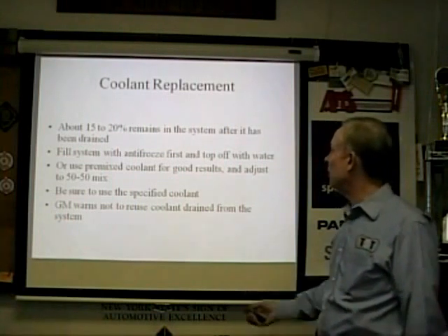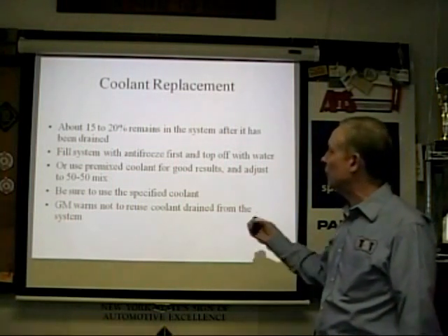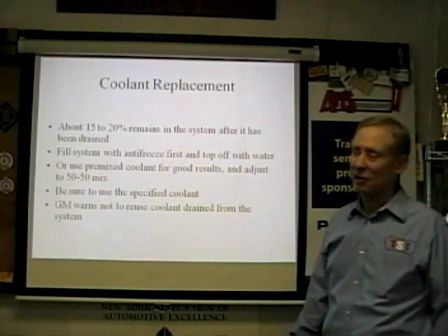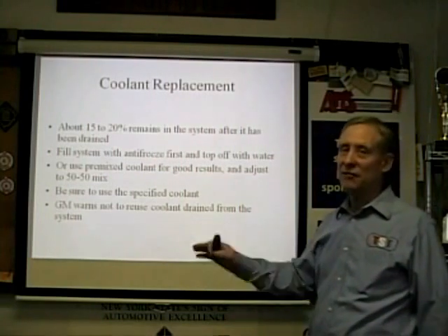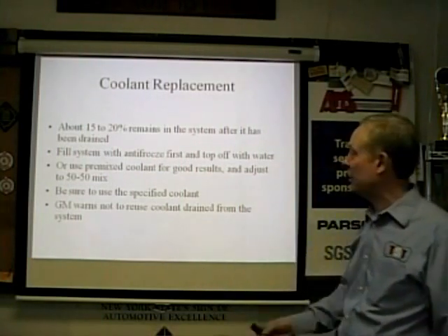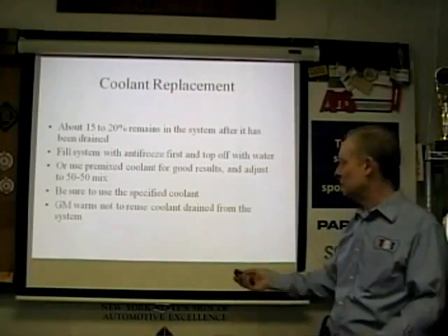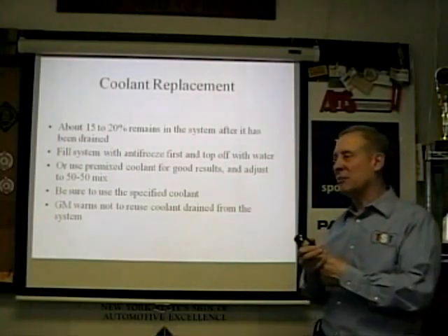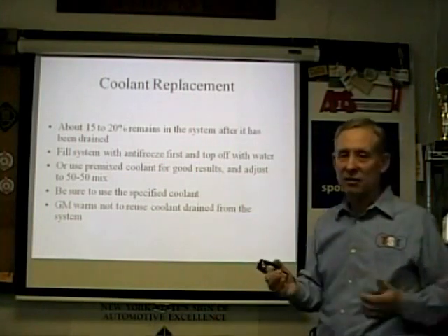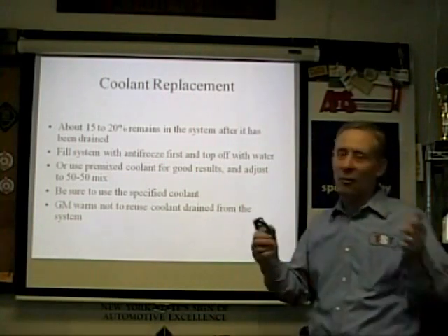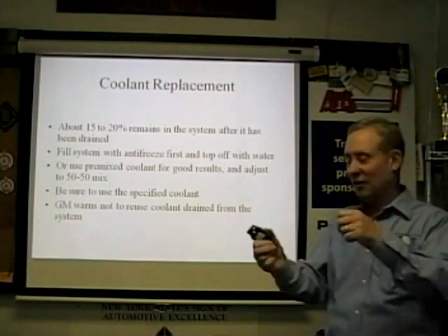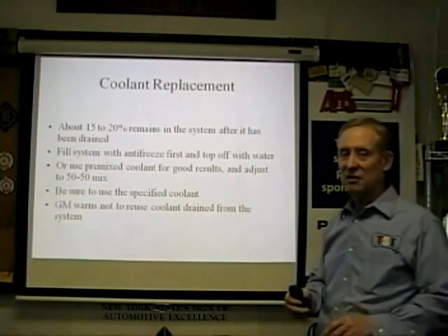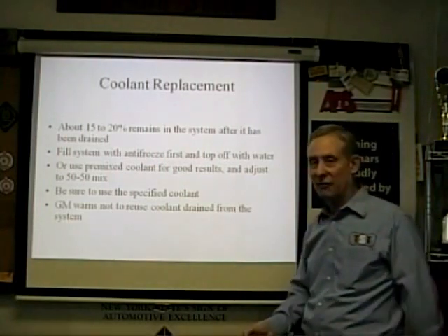Fill the system with antifreeze first and top off with water is one way. I don't like to do that. I take cans, mix them 50-50. I write 50-50 on the cans. You can buy pre-mixed that are already done. But I don't like the idea of, if I have an empty system and I know it takes 3 gallons, I'll pour a whole gallon in and a whole gallon of water in, and I'll use a gallon of the mix. But otherwise, I use the pre-mix, so I always know I've got 50-50.